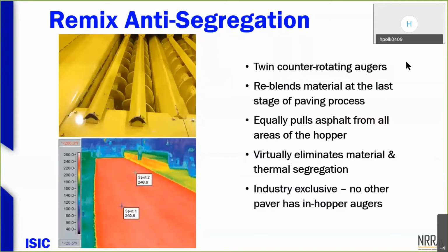But these augers have to be maintained. We'll tell you that during your wintertime maintenance, take some time to hard face these augers. You want to keep them serviceable, and they'll go a long way. Within that thermal spec, I won't quote the numbers or the Celsius temperature variances, but there are penalties, and there are also bonuses.